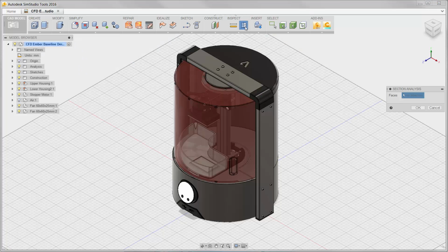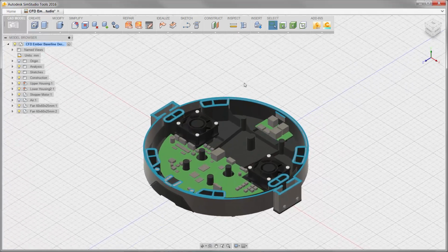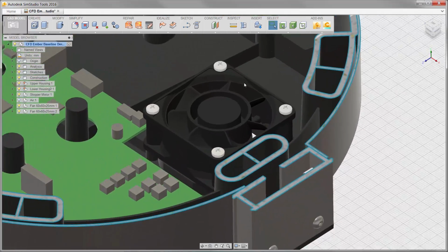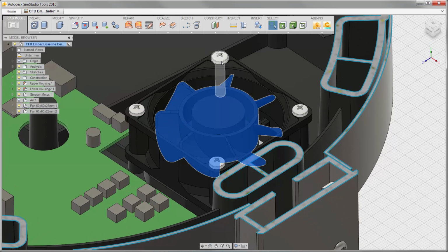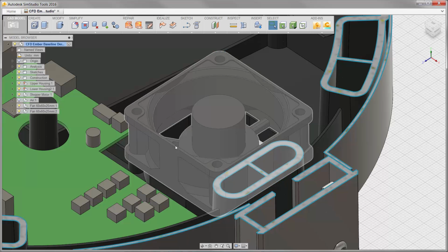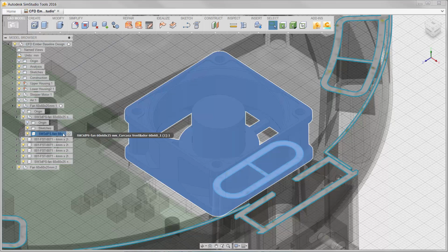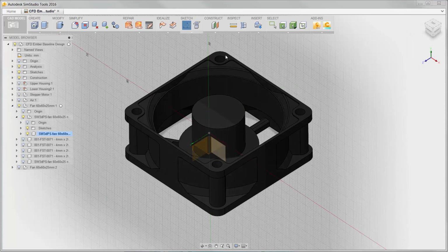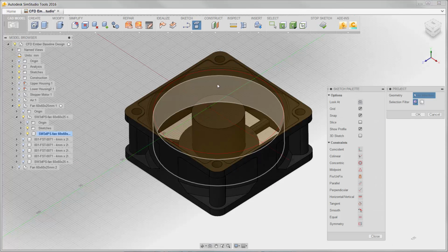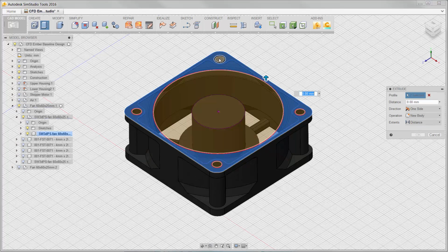Let's go ahead and take a look at them using SimStudio Tools. We will section the model to have a closer look. Like many purchased components, the 3D model can be downloaded from the supplier website, and the parts may contain components or features that are not necessary for running the CFD study. Watch how SimStudio Tools quickly prepares the geometry before sending it back for virtual testing. Taking a few minutes to remove detailed features saves a significant amount of time depending on the number of design variations we plan to run.